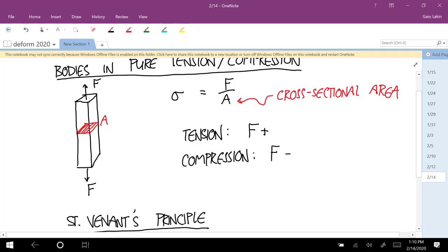If instead of being point loads, those were uniform distributed loads, so this force F was applied uniformly over the whole top and over the whole bottom, then every point really would have that stress. That makes sense, I think. You can think of it up there in terms of the tractions and stuff, and you could calculate that. But so the question is, if we go from the uniform distributed load to this point force, can we treat it like those loads are the same?